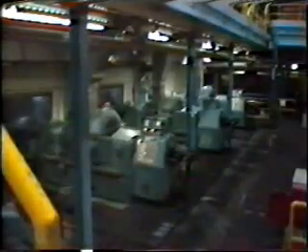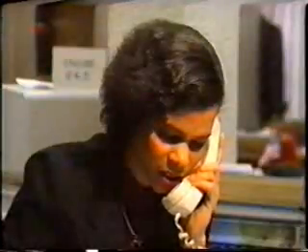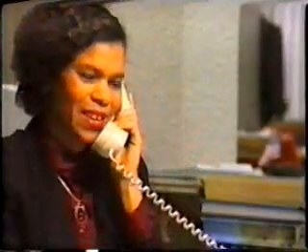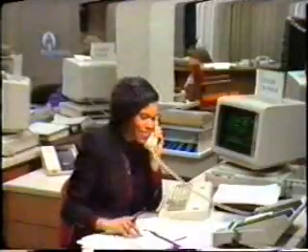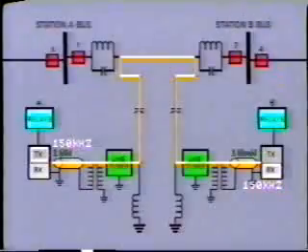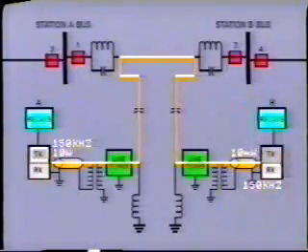Well, for one, you know that the decibel is often used as a unit of sound. You will often see reference to 85 dB on the factory shop floor or 100 dB at aircraft takeoff. It would seem logical that telephone transmission, and by extension any communication transmission, would also be measured in decibels, or dB for short. As used on carrier systems, the dB is actually a ratio comparing signal power into a circuit with power out, and by implication, an indication of loss.